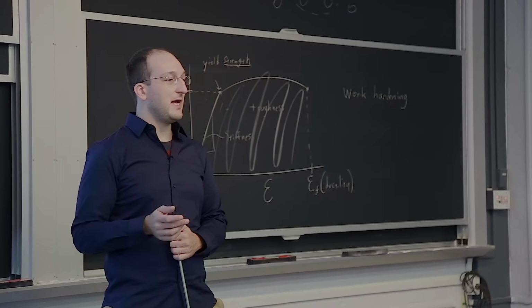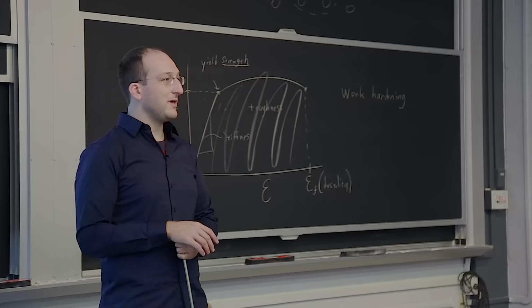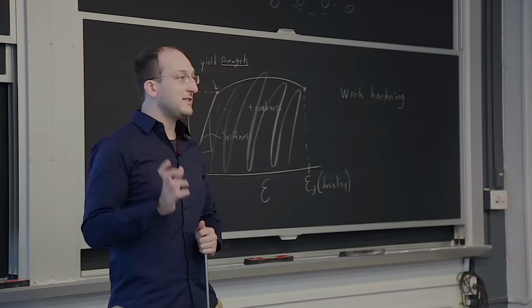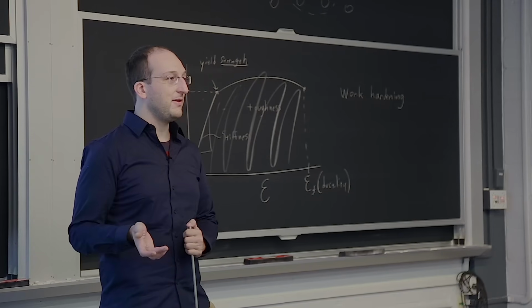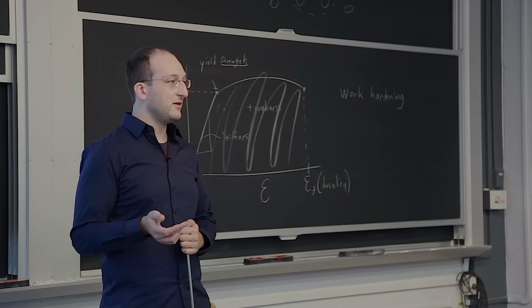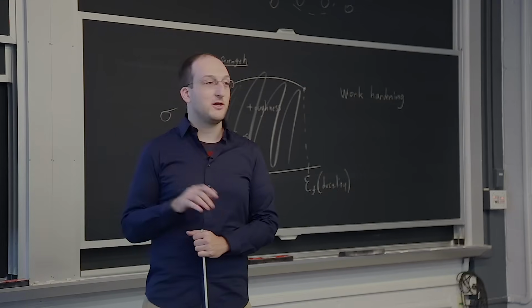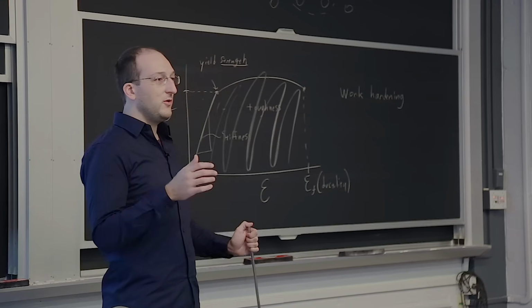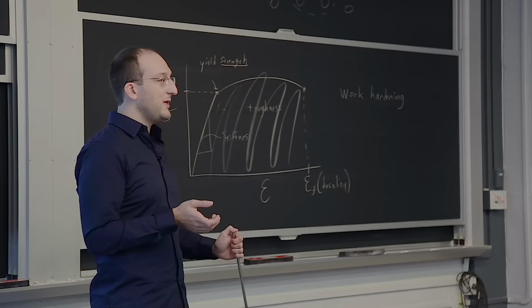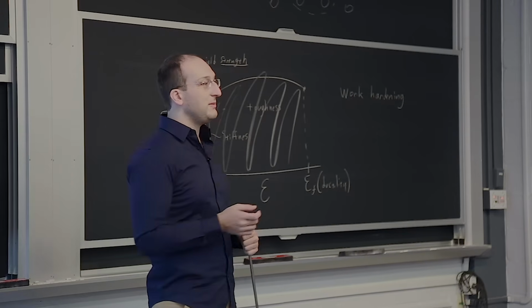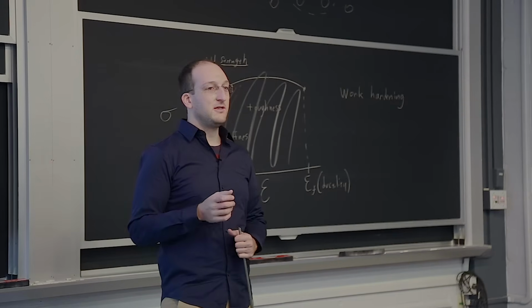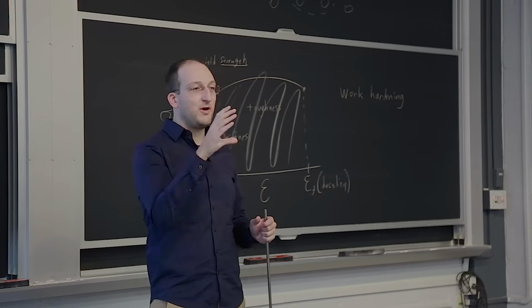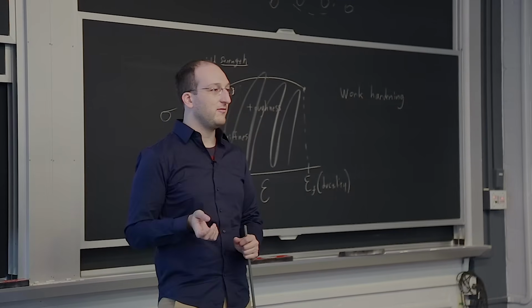So what you actually want out of a high-strength ball bearing is something that's extremely hard, resists deformation so it doesn't undergo, let's say, change of shape that would prevent it from rolling without friction, or with very little friction. You want it to be quite stiff because you don't want the load of whatever you're loading onto it to deform it, but you also don't want it to be brittle. So it's got to be somewhat tough and ductile to prevent sudden failure. You'd rather it compress a tiny bit than just cracking in half.